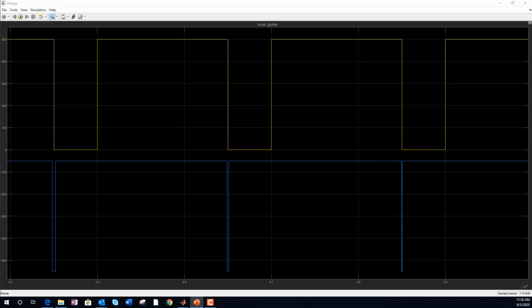You can see that while the voltage response using the global solver accurately captures pulse width, the voltage response using the local solver cannot capture a pulse width smaller than the defined sample time, which in this case is 50 microseconds. Engineering judgment is needed to determine the trade-off between simulation speed and accuracy for a given local solver setting. As a general rule, you need to set Simscape to local solver in order to deploy to a real-time system